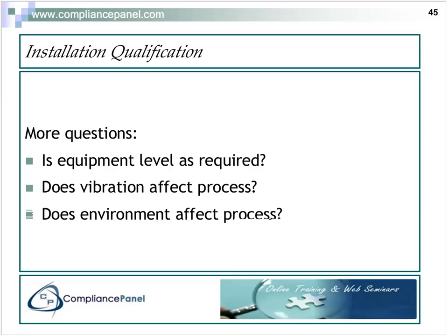Want to make sure that equipment that's producing parts is producing them to the correct configuration, and most often things that affect that might be things like level equipment. Vibration. Does vibration affect the process? Environment, and again, that's temperature, humidity, and maybe even things like if you have an RF welder in the area, is there RF floating around that might affect the results?